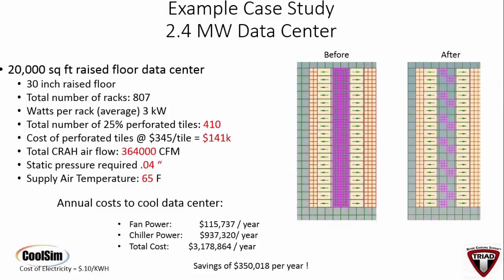We want to slow down at 7 feet and create a bubble, like a ceiling lid there. When you get too high of stratification, that's all driven by static pressure. If you're getting static pressure 0.05 and above, you're going to see a throw above 7 feet. You're going to get up to 8 or 9 feet.